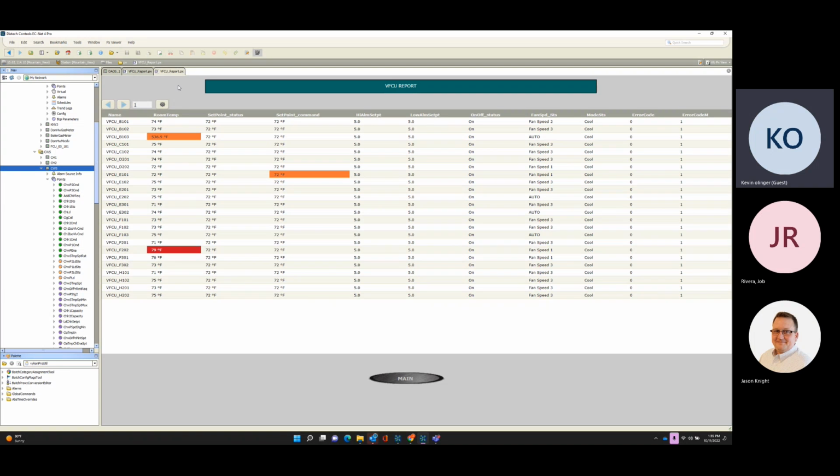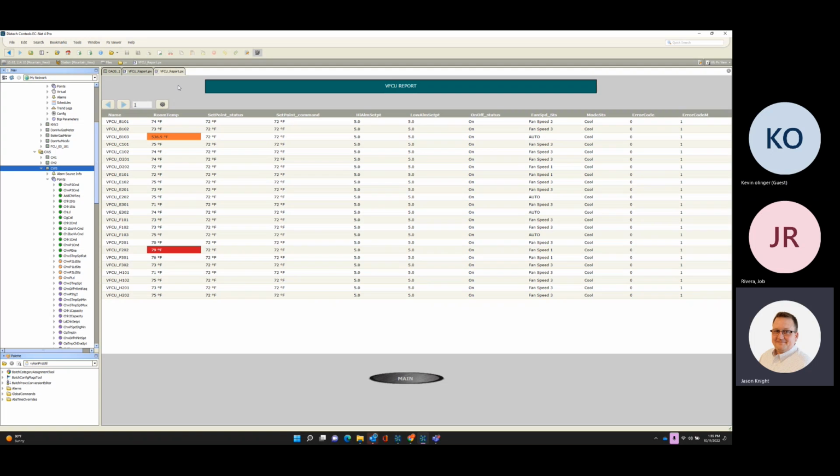So with the air handler overridden on, with its chilled water valve open more than X%, whatever, the chillers were still enabled, but I'm assuming that the outside air lockout would still be in play to keep them from running if it's too cold, correct? Yeah, if it goes below whatever we got it set at, I think right now it's like 54 degrees or something,